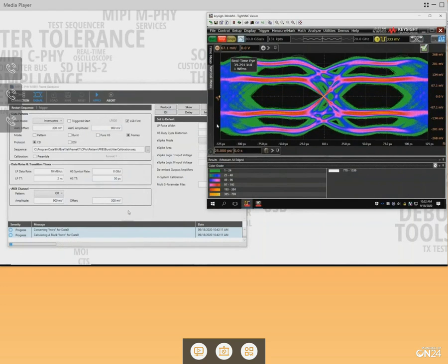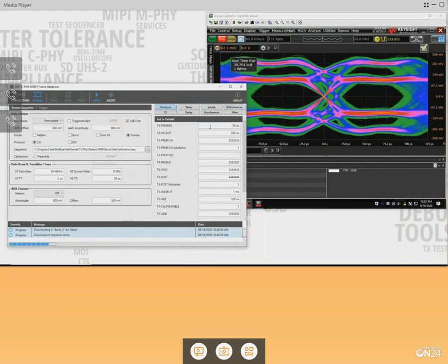And again, while we are waiting for a little while, a little bit more explanation here on our left-hand side. I can of course select all kinds of different sequences following different protocol standards, either for CSI or DSI. We can of course also select various protocol sequences that are then generated here. So we are not only generating a physical eye diagram signal, we are generating real traffic here for MIPI C-PHY following the various standards that are then using the C-PHY standard here. And also, for example, here we have the protocol timings when it comes to high speed and low power changes and so on, but this would lead too far for this quick demo here.